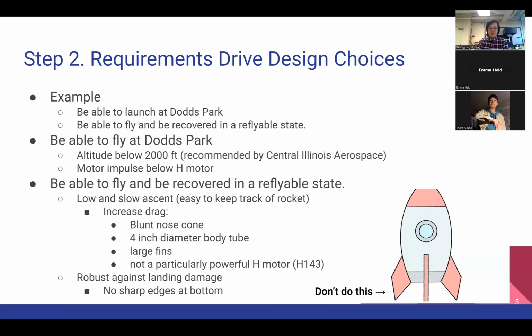The last thing to keep in mind is you need to be robust against landing damage. I guess the two greatest stresses that a rocket will experience are, during ascent, the aerodynamic forces. But if you're doing your L1, you're probably not going to reach supersonic speeds, so your aerodynamic forces are going to be kind of low. And I think the majority of damage comes from landing itself, especially hard landings.